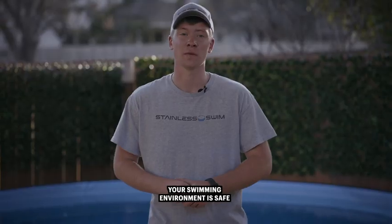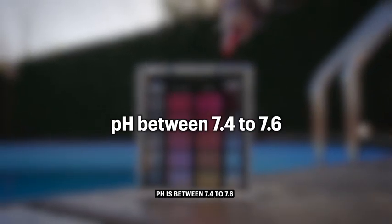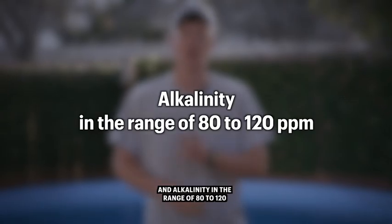To make sure that your swimming environment is safe, keep chlorine in the levels from 1 to 3 parts per million, pH between 7.4 to 7.6, and alkalinity in the range of 80 to 120.